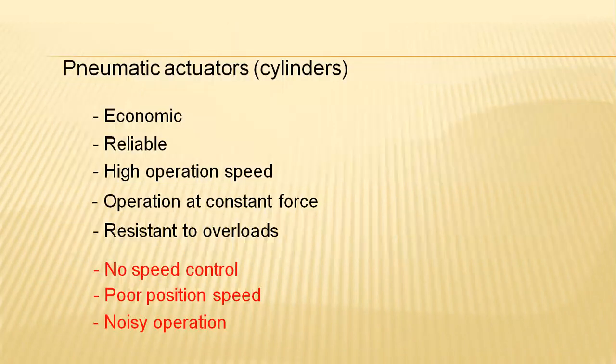Coming to the positives and negatives of these pneumatic actuators. It is economical in construction at the initial stage, and it is reliable, and high operational speeds occur. Random movements take place, operating only at a constant force, but not in an incremental or decremental manner. So straightaway quick actions take place in the pneumatic case. Finally, it is resistant to overloads.